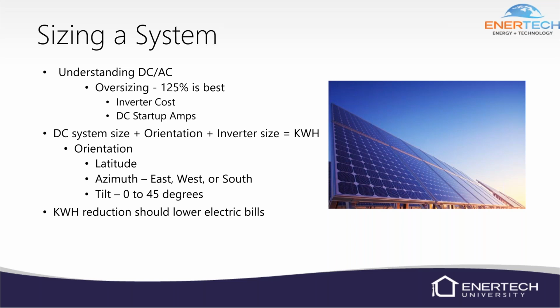What we have noticed here lately is that the inverter, if we have one utility that I can think of offhand that has a cap of 10 kW DC. So usually they're 10 kW AC, but it's their bylaws. It is what it is, because I personally disagree with that. But what we do in that case is we get as close to 10 kW DC as we possibly can, but then we use the 7.6 inverter that would bring us down a little bit.